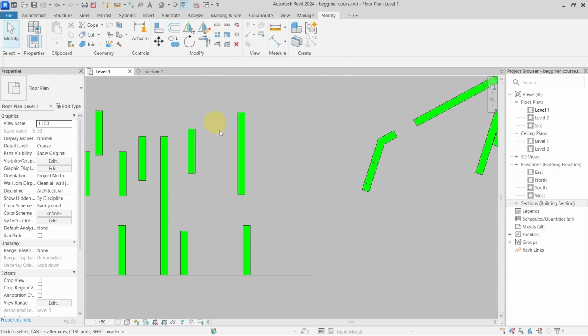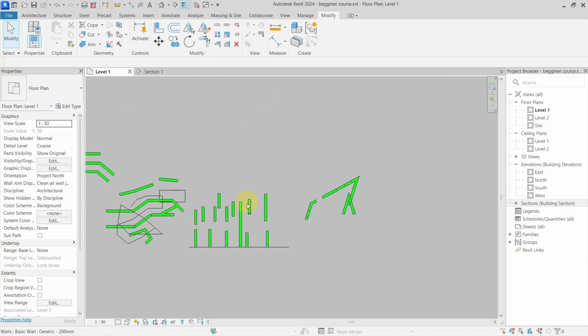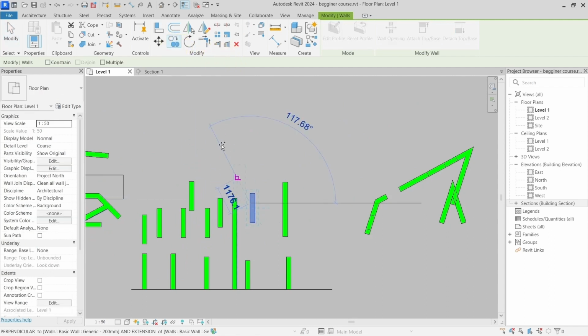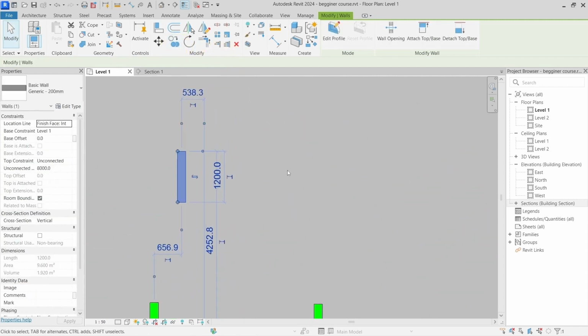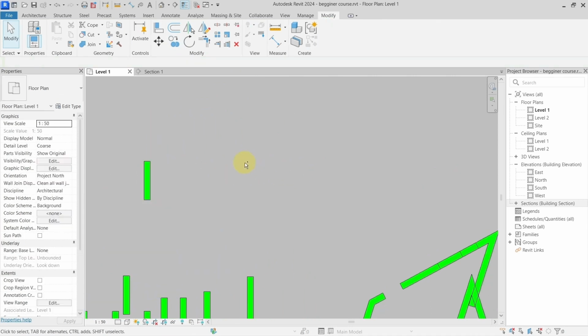This is also pretty handy. This thing can actually speed up a lot of your modeling. So let's just now copy this here. And let's imagine that I want to create 10 copies of this wall, which will be running in this direction, and they will be all spaced the same distance, let's say 1000 millimeters.